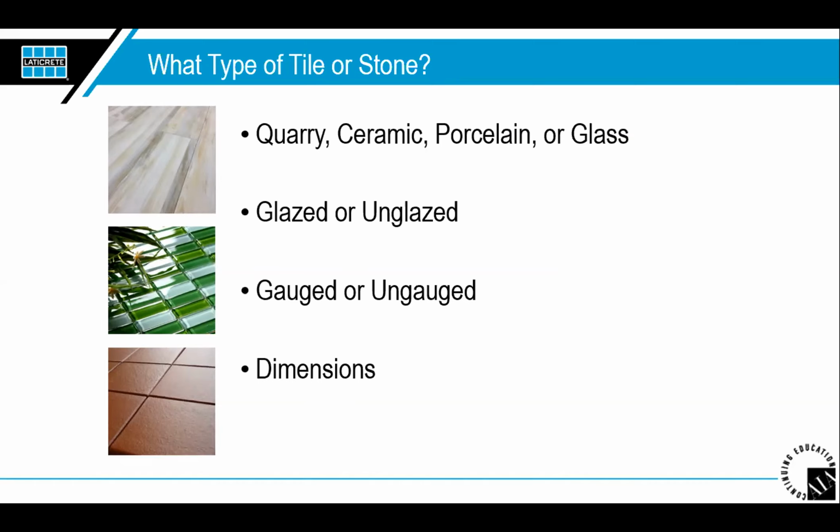So you have many different finishes, colors, textures that can be achieved by glazing tile, right? Glaze can also provide slip resistance and some light chemical resistance as well. Glazed tile is easier to grout than unglazed, right? So we actually have a surface on top of it that would allow the grout to kind of glide around, be easily moved by the installer. I don't know if the slides are actually going to talk about it, but we also have a lot of sealers that can be used to seal the natural stone and seal the tile, or even use a grout release, for example, that would allow us to grout easier as well.